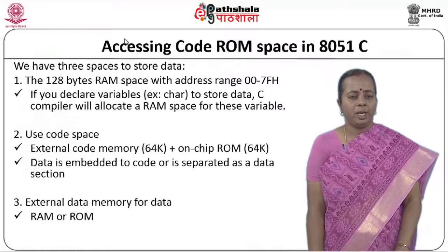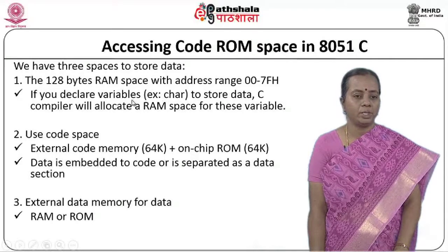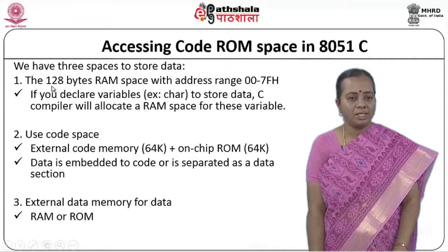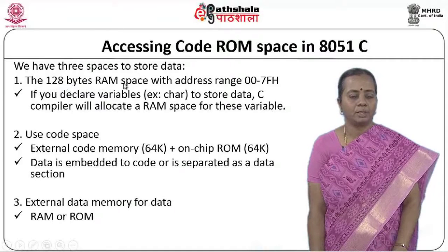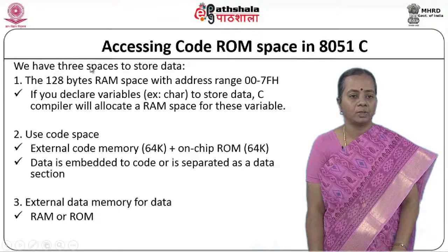When you are looking at this kind of operations, we will be looking at the memory space also. When I am looking at memory space, we know very well that with your 8051, we have only the RAM space of 128 bytes. So, at the maximum I can store only 128 bytes, but sometimes it may not be possible to store within this particular area. So, by the time we can use the code space also.